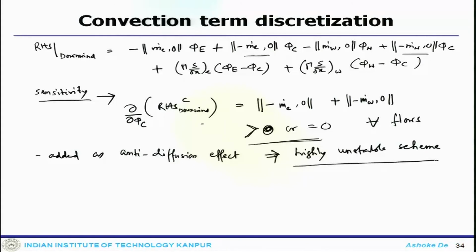So, on one hand you get the upwind scheme, which is stable but of lower order accuracy. The CD scheme has some sort of problem, and this one is unstable and, by the way, also first order accurate.